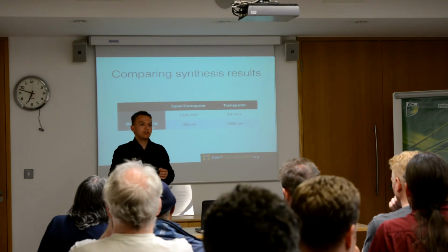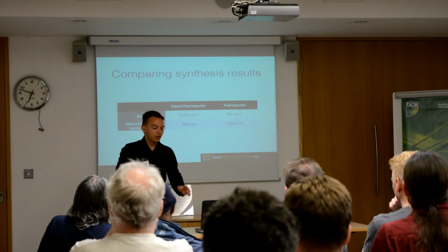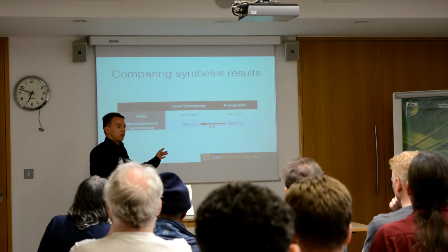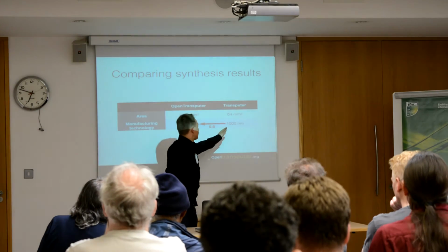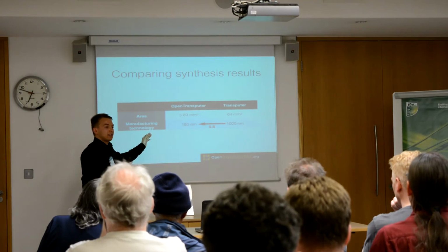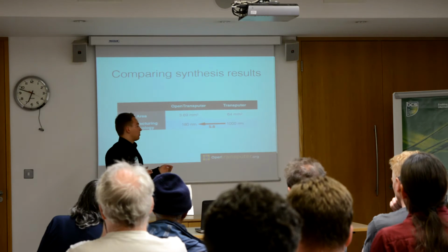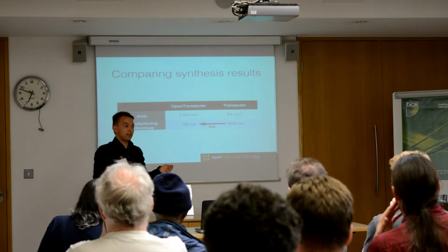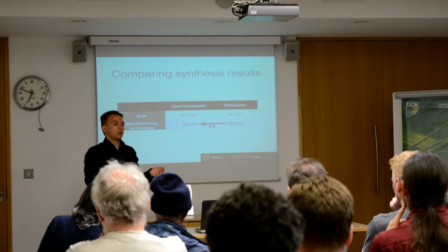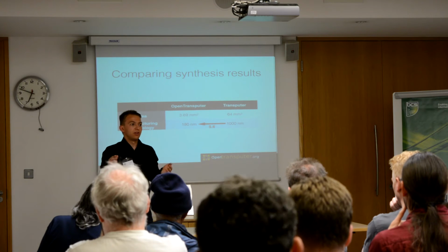There's also an interesting observation to be made regarding Moore's law. The original Transputer was manufactured in a 1 micron or 1000 nanometer process, as we can see here in the table. By scaling this down to 180 nanometers, we have improved the manufacturing process by a factor of 5.6. Now, if we assume that the OpenTransputer was the exact same processor as the original Transputer, meaning it would